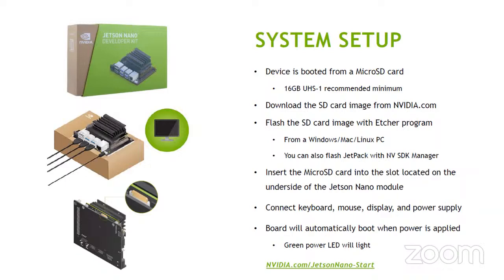So in that case, you can create swap RAM space. That means you can use your SD card memory as RAM. You can allocate some of your SD card memory, you don't have to allocate the whole memory. You can just allocate some of it, like 4 GB or 6 GB, and serve that as swap memory. Swap memory means once the inbuilt RAM is full, it will write data to the swap memory, so the system will never crash because of an out of memory error.